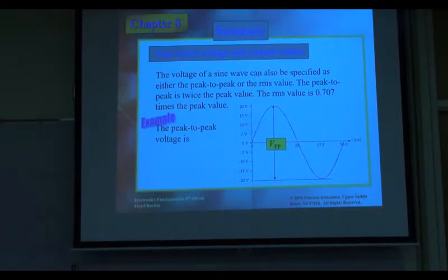Alright, example here, the peak to peak value is 40. The RMS value is... for this example. If the AC peak is 1, it is 0.707. So it's 70% of the peak. So what is the RMS value here? 20 times 0.707, right? Make sense? So it's like 14.14, right? Okay, so 14.1.